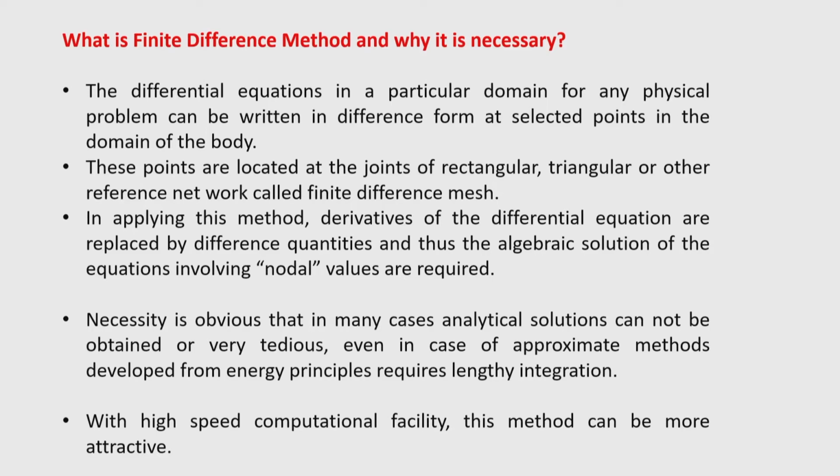For example, in case of a rectangular plate, say A by B, if I divide the lengthwise direction into, say, 100 divisions, and the widthwise direction I can also divide into 100 divisions or maybe other numbers also. In that case the intersection of the orthogonal lines will give you the nodes, and at these nodes the values of the deflections are calculated from the solution of the algebraic equations.